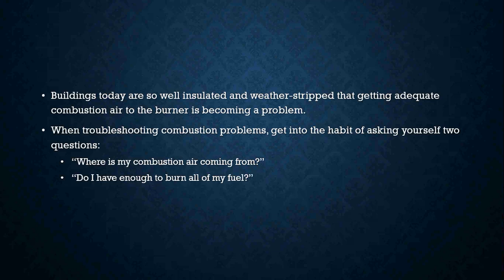Because today, a lot of our newer buildings and homes are being insulated a lot better than the older ones. Okay, they're weather stripped, they're well insulated, and getting adequate combustion air to the burner is becoming more and more of a problem. In fact, for a lot of our newer buildings today, especially newer homes, it's now actually a code. You have to bring a certain amount of outside air into that home to help support the air quality in the home.